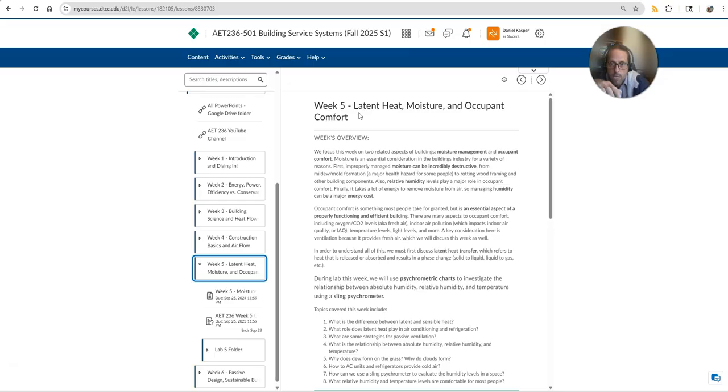Remember, to heat up 1 pound of water 1 degree, it's 1 BTU, and then another degree is another BTU, and so on. So you add 1 BTU per pound per degree, you get it up to 212, and then it exists as what's called a superheated liquid. It's not steam yet when it reaches its boiling point. After it reaches its boiling point, you need to add 970 BTUs to vaporize that whole pound.